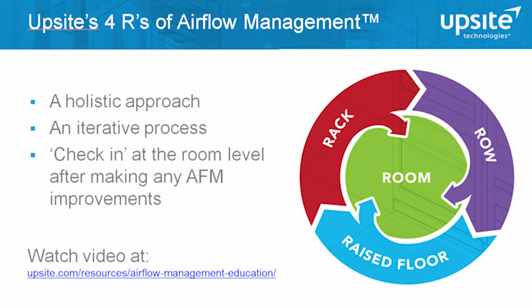So look at the raised floor and really quantify how many square feet. You can just do the math and figure out how many square feet of open area there is in cold aisles and how many square feet of open area there is in all the other locations. And that's a very simple metric for helping manage the raised floor open area.